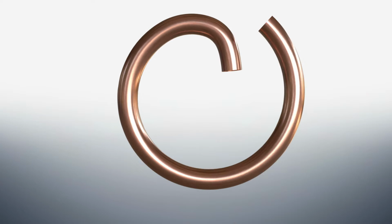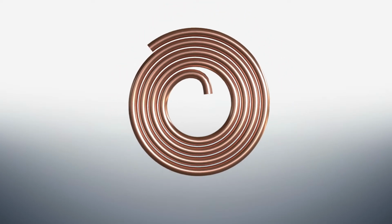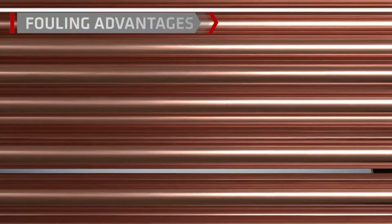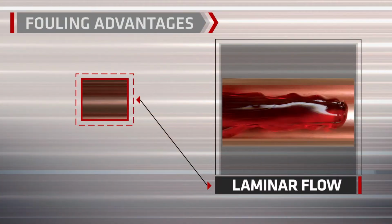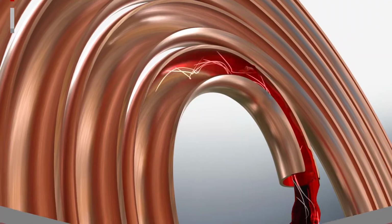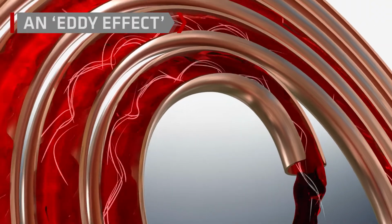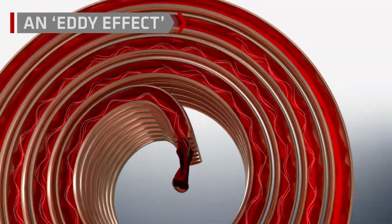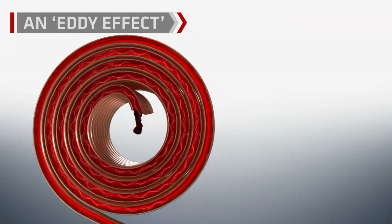The spiral flow path of the Heliflow ensures that you get turbulent flow. Low flow rates that occur in a straight shell and tube design can cause poor velocity and result in laminar flow. With the Heliflow design, you get an eddy effect, constantly turning the fluid over as the fluid travels through the coil, ensuring a consistent turbulent flow path.